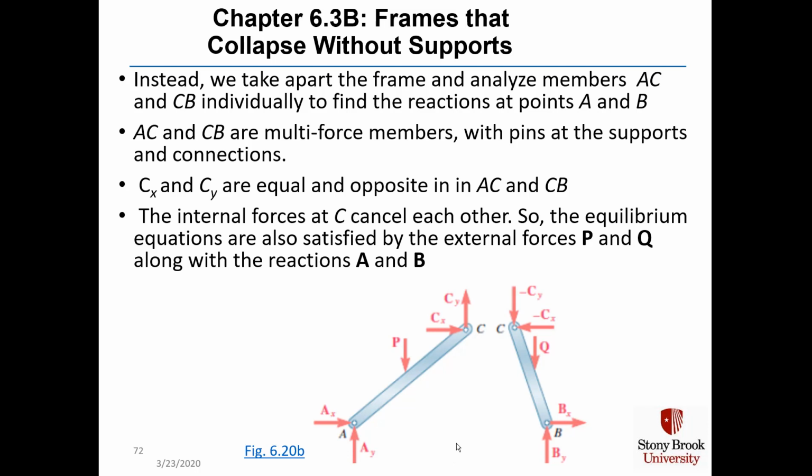CX and CY are equal and opposite in the two members, as shown here at the top. And these internal forces at point C will cancel each other, so the equilibrium equations are also satisfied by the external forces P and Q, along with the reactions A and B.